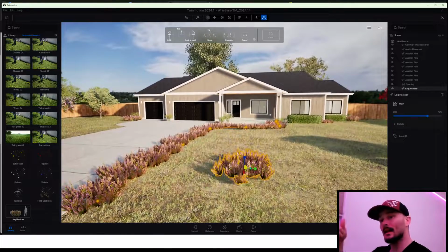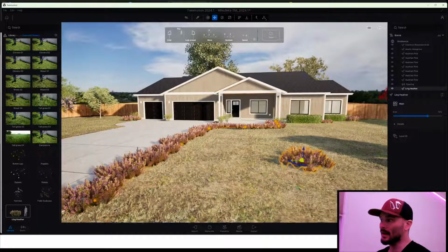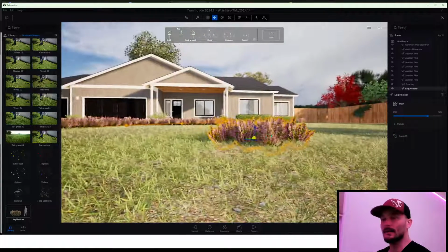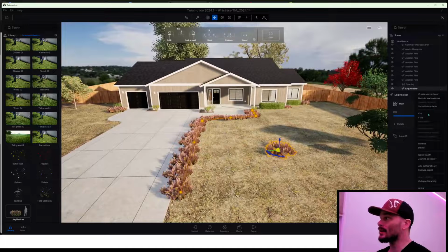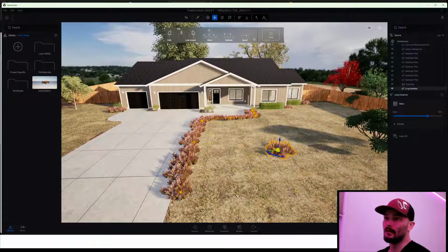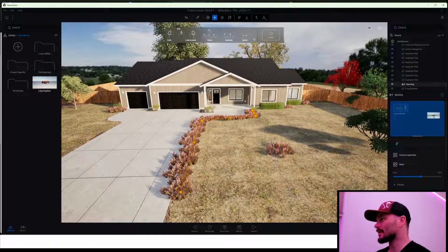I'm raising it up so that when we get off of this editing mode and we go to place this, if I were to just shift click somewhere, notice now that it's really diving into the ground. That's because it's seeing a new Z offset. So now that I have that set up the way I like it, I could add this to my library and then go seek this out of my library and see that I have this placed in my library and come back into our spacing, drop this into spacing.